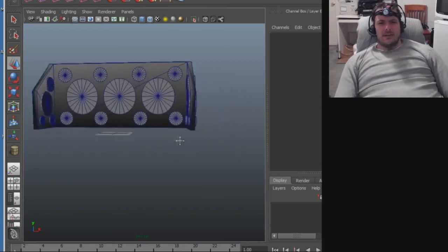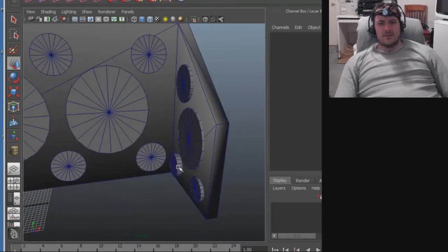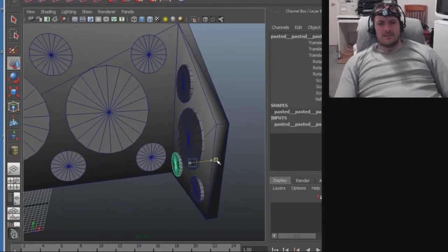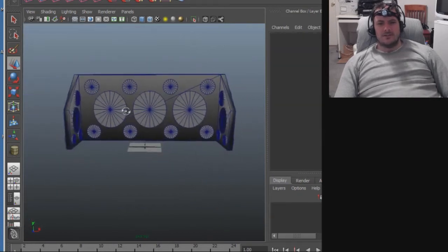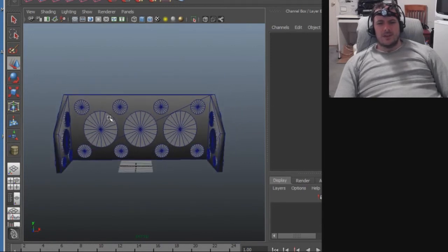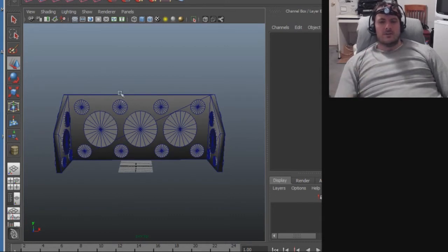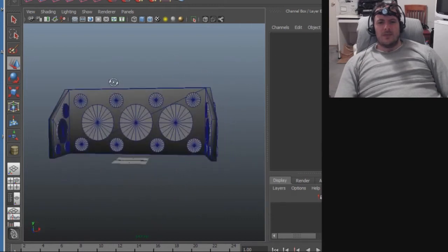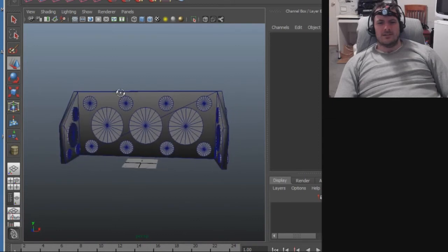Now, you can avoid all of this by getting a 3D printer enclosure that keeps the whole print heated and prevents the warping from happening to begin with. But that enclosure is putting a lot of heat onto all of your servo motors, onto your heat bed, onto your model, onto everything. And that can cause all kinds of new problems electrically and cause your servo motors to burn out prematurely. Or not your servo motors, your stepper motors. So that might help to prevent warping, but it might, in the end, do more damage than it does good.